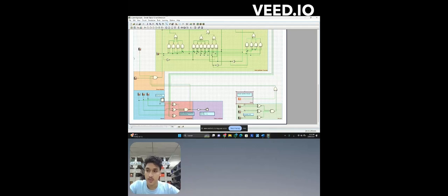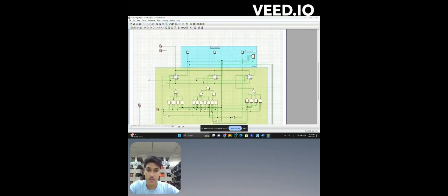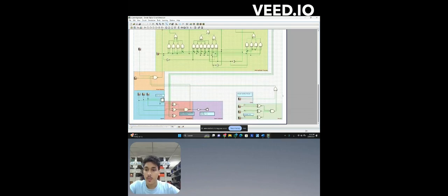As my friend Muhammad said, the clock enabler has 4 rules. He talked about 2, and I'll talk about the third one, which is the comparator. The comparator compares the input floor and the current floor. If the input floor and the current floor are equal, the output will be low, 0, and the clock enabler will not work. If they are different, the output will be 1, and the clock enabler will work.